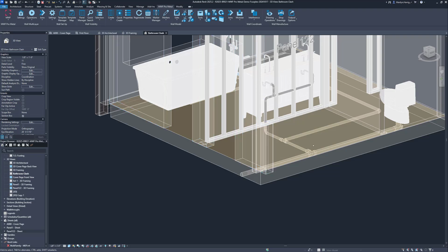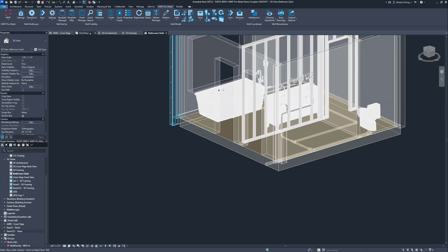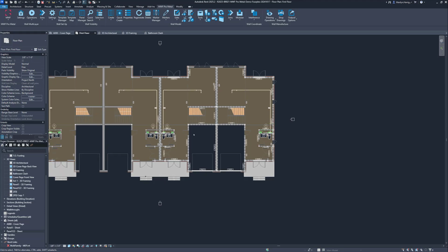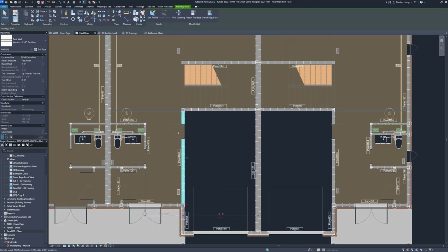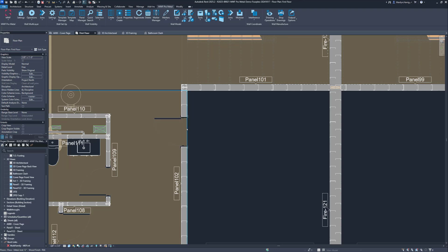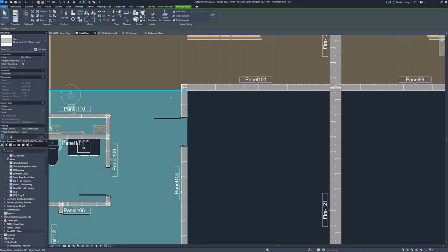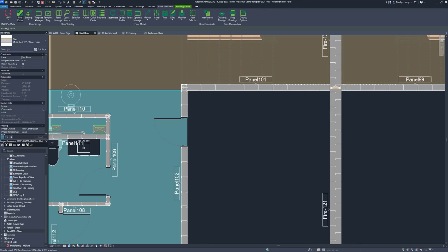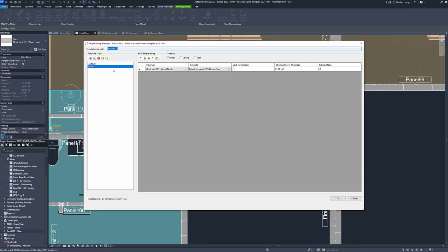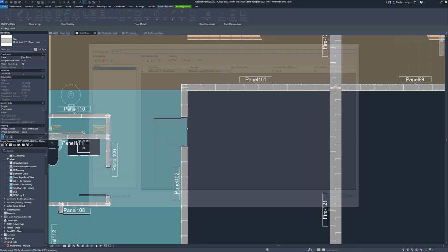Now here you can see I do have a floor. So we're going to go back into our first floor there. I'm just going to select that floor. And then from there, I'm going to go into my floor module. I am going to use the quick create option that we have, the same thing that we have in the walls. So there, I have already set it up.